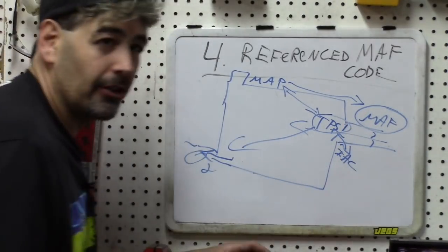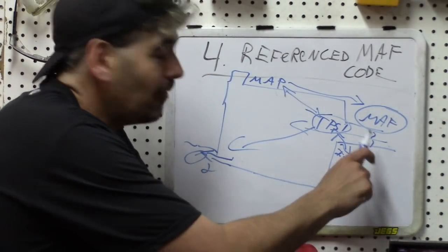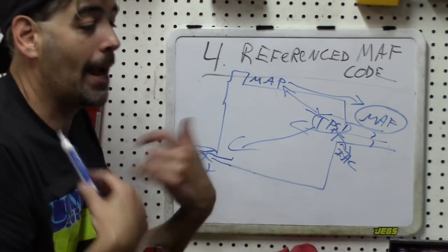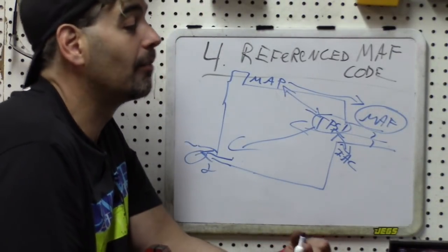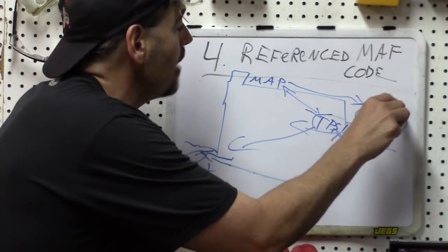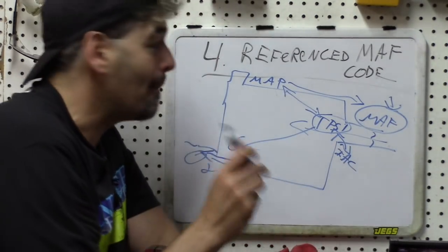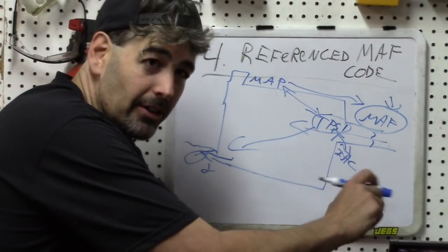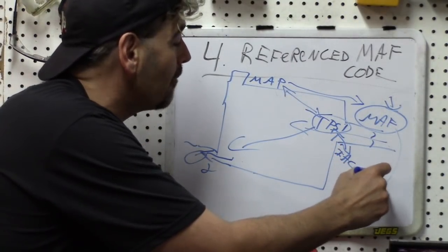So before you replace a MAF sensor, again, I have yet to see a problem where replacing the MAF sensor fixed a problem, out of my own personal experience, out of dozens of people on this channel, and out of literally hundreds on chat rooms and forums. If nothing else from this MAF video series, you are unlikely to have a mass airflow problem, especially if it is related to some type of air induction issue that you suspect, except for a hot wire MAF being dirty.